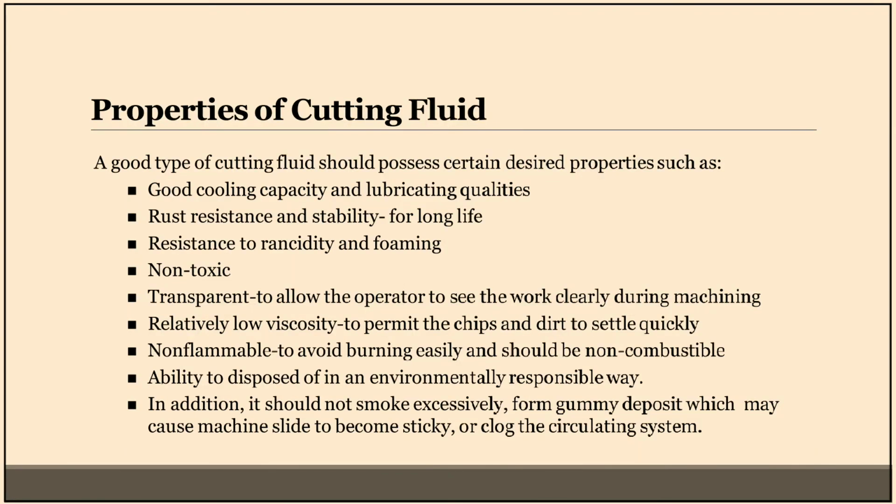Properties of cutting fluid. A good cutting fluid should possess certain desired properties such as good cooling capacity and lubricating qualities, rust resistance and stability for long life, resistance to rancidity and foaming, non-toxic, transparent to allow the operator to see the work clearly during machining,